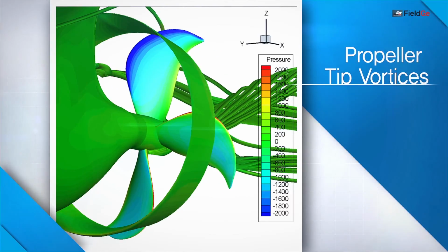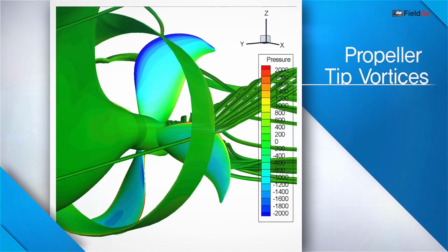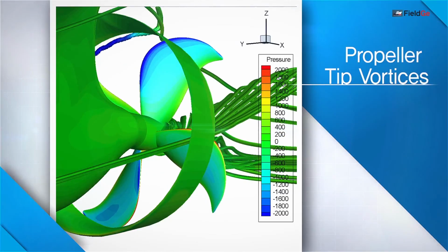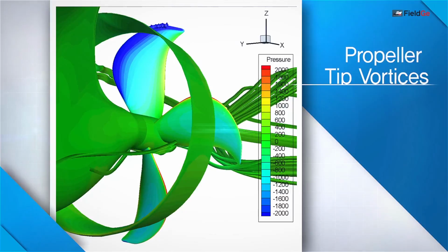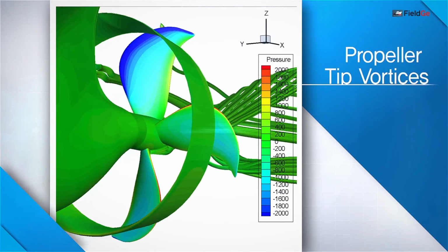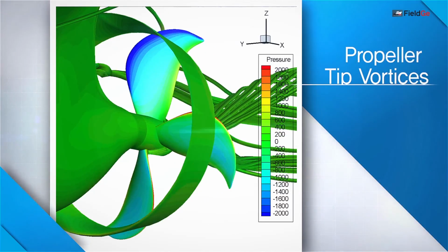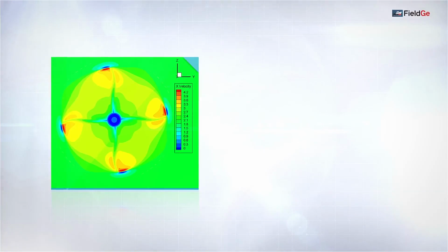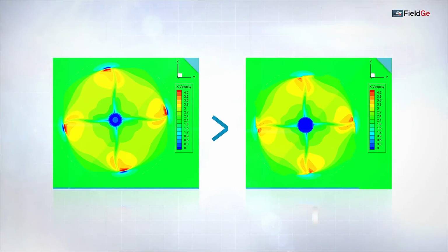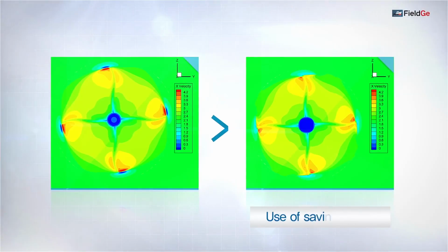This high pressure zone in the propeller plane is mainly observed in the region between the 10 o'clock and 2 o'clock. Pressure distribution of the low negative pressure is also observed in the same areas. The figure on the right side shows the velocity distribution changed when attaching this saving device. Blue at the end position near the propeller denotes a zero speed. In other words, a U-velocity is zero in this area while the flow rotates.